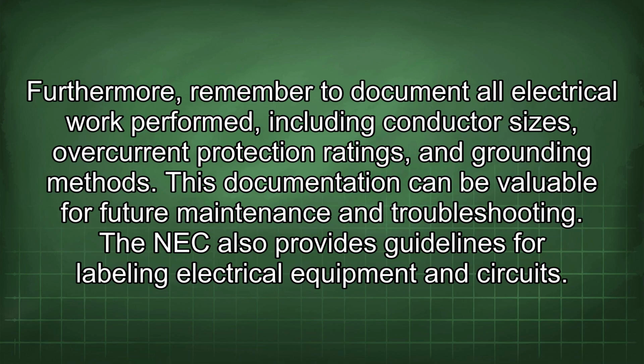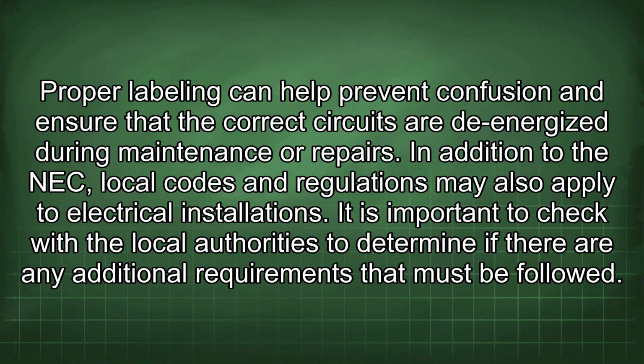Furthermore, remember to document all electrical work performed, including conductor sizes, overcurrent protection ratings, and grounding methods. This documentation can be valuable for future maintenance and troubleshooting. The NEC also provides guidelines for labeling electrical equipment and circuits. Proper labeling can help prevent confusion and ensure that the correct circuits are de-energized during maintenance or repairs.